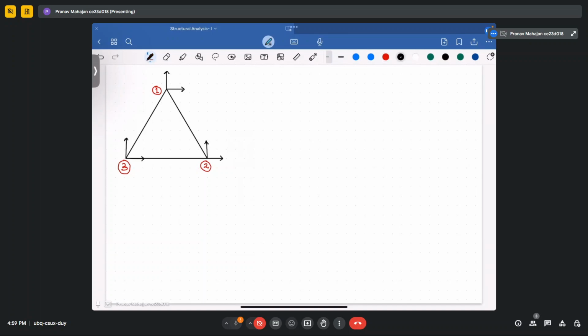By solving the problem you will get to know how you can number the truss or a beam element, how much complication you will observe when you change the numbering system, and how much easier it gets if you make node 1 the one which has no supports, because the other supports will get 0 and the only part that will be remaining will be only node 1.